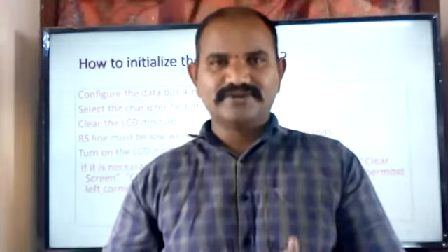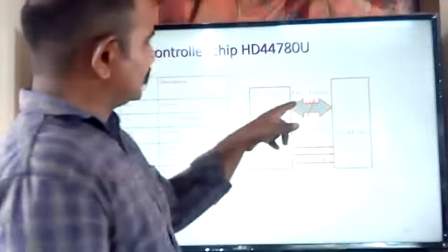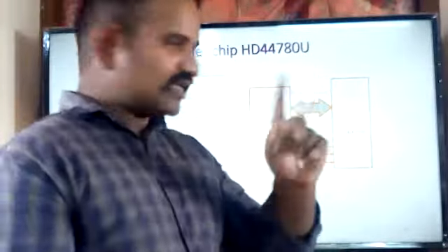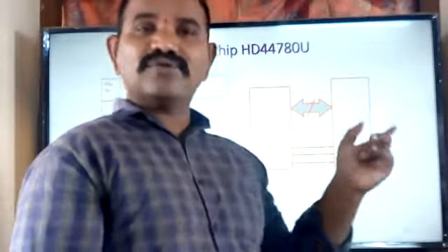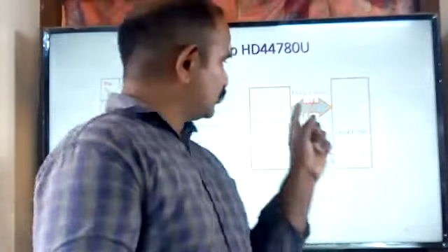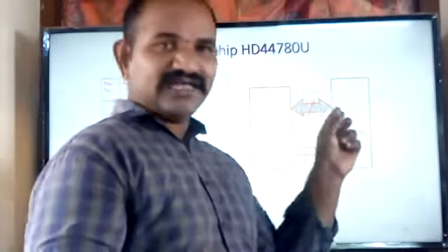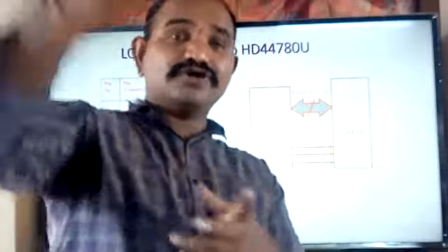Let us suppose I would like to print the number 6 on the LCD module. If I am sending 06 on this particular line, it is not going to be recognized by the LCD module. If that 06 which we are sending is the ASCII value for some other element, then that value is going to be displayed on the screen, not your 6.